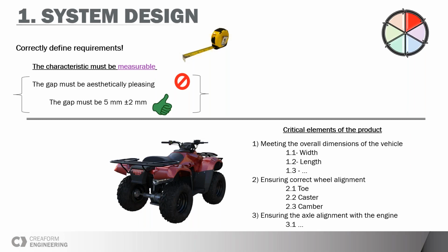So what 3DCS, or a dimensional management software, will do is you can put a variation on that, and then you can virtually assemble with all the tolerances, and at the end of the day, what you end up with is a stack up of all these tolerances you have, and then you can make scenarios on how your product may vary depending which part is at the end of its own tolerance boundaries.